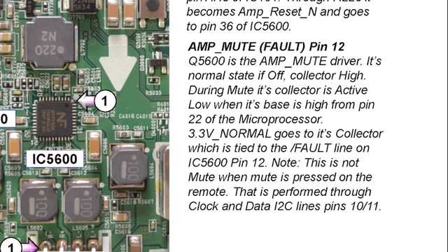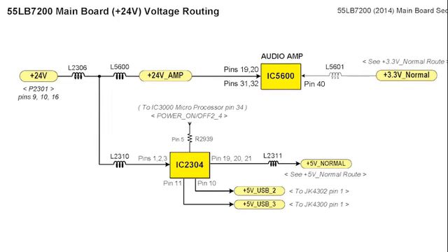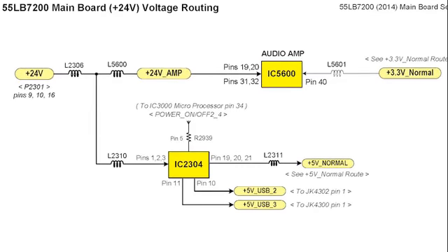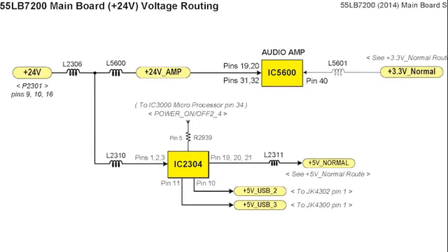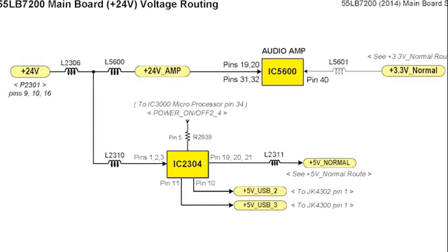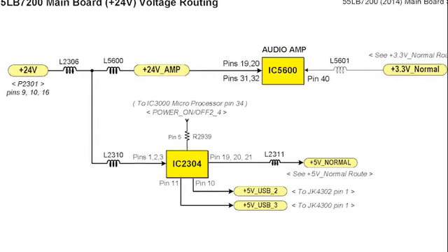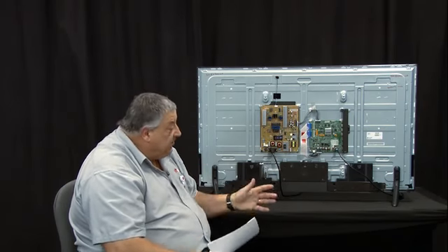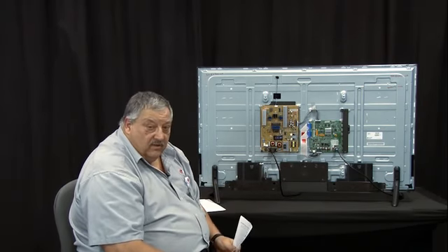And there's a breakdown even further on page 817, which shows you the signal flow, so you could follow that for all the voltage levels going into that audio amp. So good detailed information and detailed digging, if you really want to get in and prove the main board is the fault and what's causing your issue.